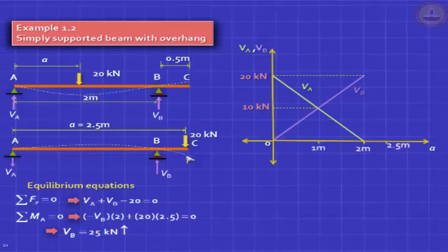You get a higher reaction because you remember that counterweight we discussed earlier, because the beam wants to lift up from the left support A. It wants to lift up and you have to hold it down. And that's what the reaction VA is doing, holding it down. It's actually pulling it down by 5 kilonewton downwards. So that 5 kilonewton is downward. The load 20 kilonewton is downward. For equilibrium, something upward, 20 plus 5, should act, and that's going to act at B. That's the reason why this is happening.